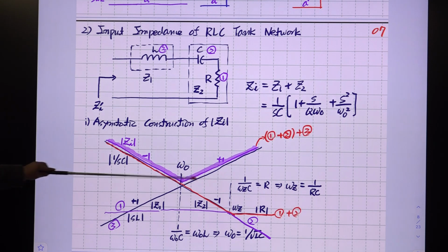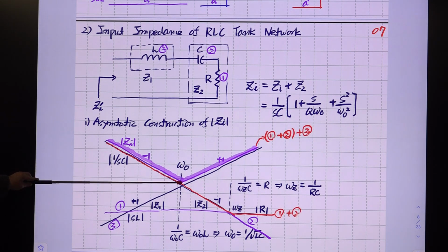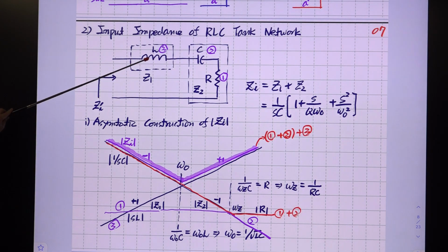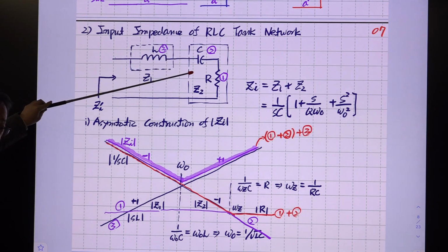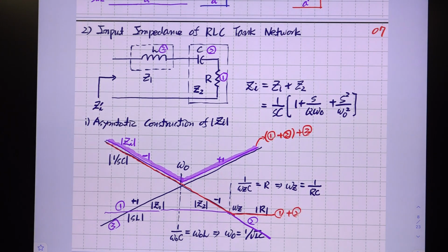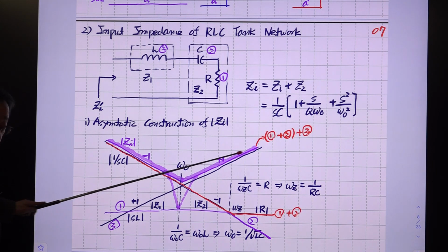Now how about this value at this resonant frequency? This value, we have perfect cancellation between this L and C. Then at this particular frequency, the impedance is simply R. Okay? So it should go down to this point at the resonant frequency. All right? This is the plot of input impedance of this circuit. Right? It follows this and goes down to this. This is the R line here, goes to R and goes back like this.